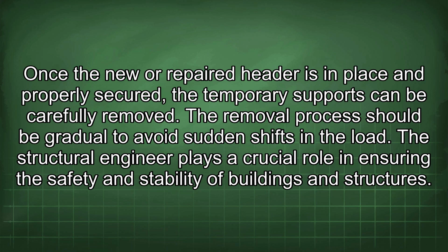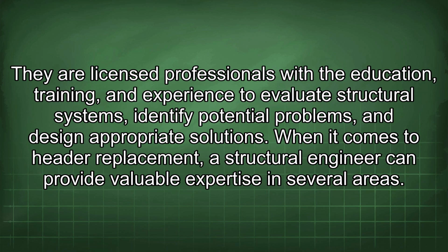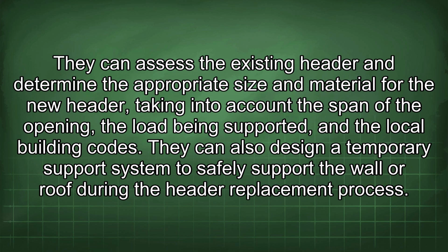The structural engineer plays a crucial role in ensuring the safety and stability of buildings and structures. They are licensed professionals with the education, training, and experience to evaluate structural systems, identify potential problems, and design appropriate solutions. When it comes to header replacement, a structural engineer can provide valuable expertise in several areas. They can assess the existing header and determine the appropriate size and material for the new header, taking into account the span of the opening, the load being supported, and the local building codes.